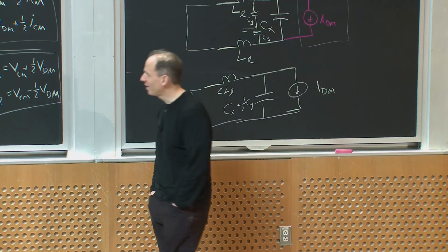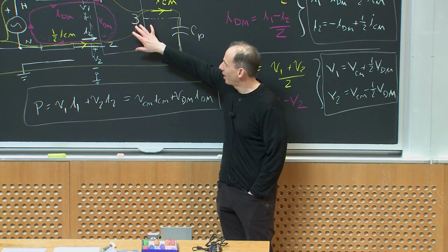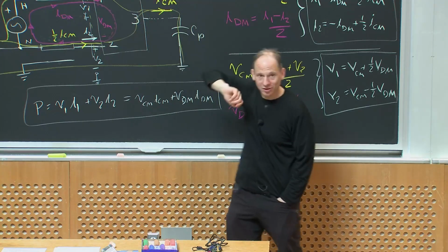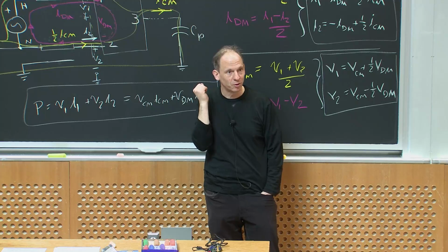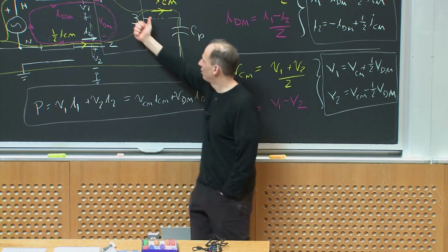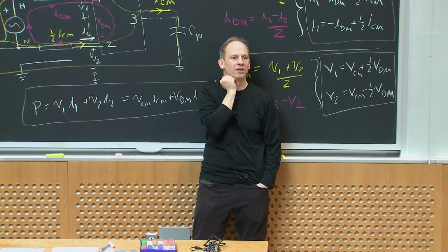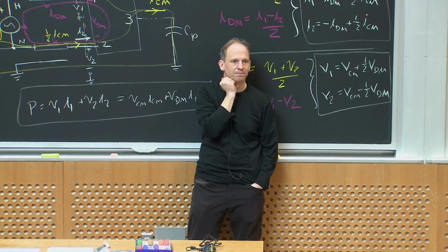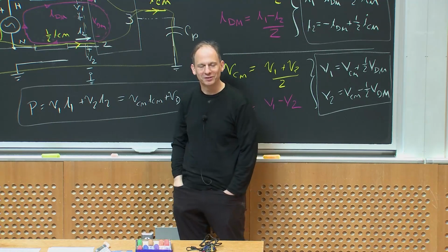So if I suddenly increase the parasitic capacitance of my transistor to ground, suddenly I'd probably see a bunch of common mode noise there too, even if I have a differential mode component. Okay, so if I'm making this third terminal current path easier, that's probably going to lead to common mode noise, for example. But no, they occur together. You've got to filter both at the same time.